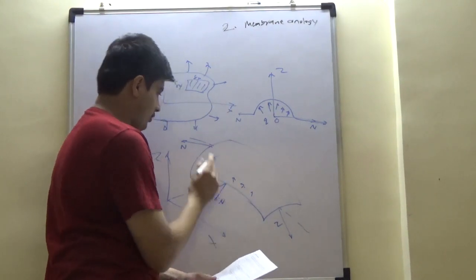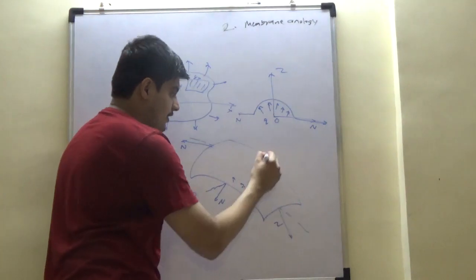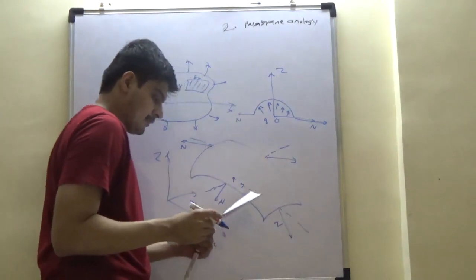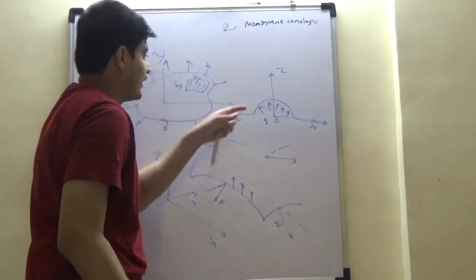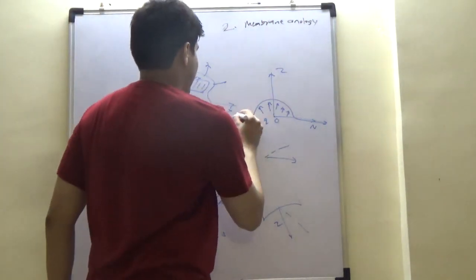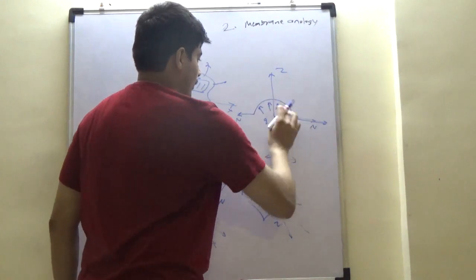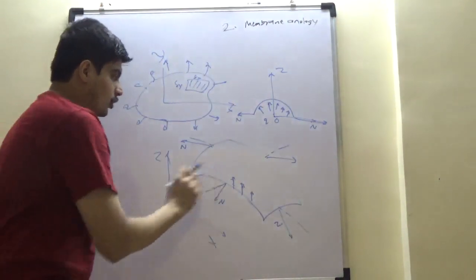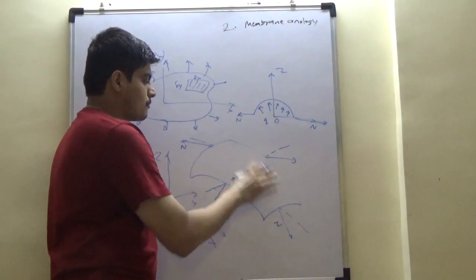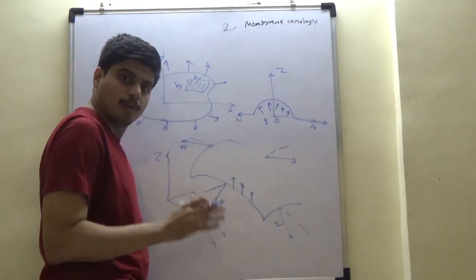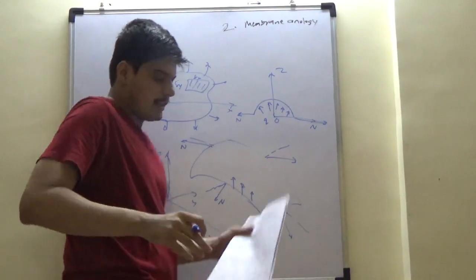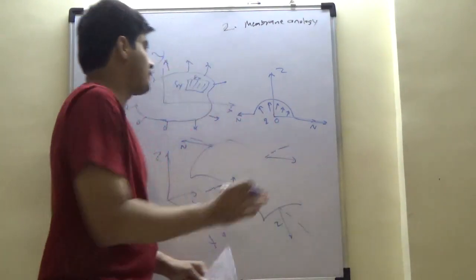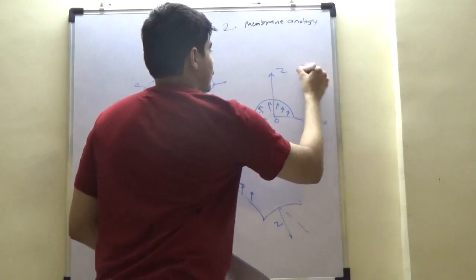These are the surface normals at the surface, and these are the reactions. N has to offset the projection of the component of this cube such that the load Q, which is a uniformly distributed load per unit area, is balanced by this. Now, in the membrane analogy, the vertical displacement in Z is W.